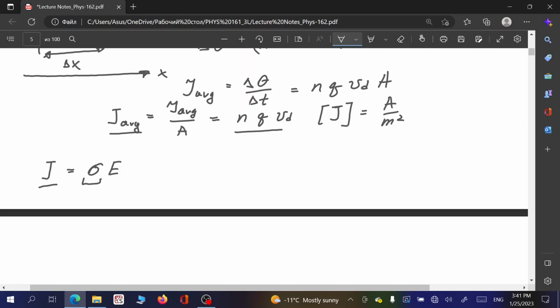However, specific conductivity of copper is noticeably higher, and that's preferable, because otherwise, in order to have the same resistance, you need thicker aluminum wires, and sometimes it's not practical. So copper is the cheapest, most technological, and quite conductive material. That's why it's used pretty much everywhere. But silver conducts better.